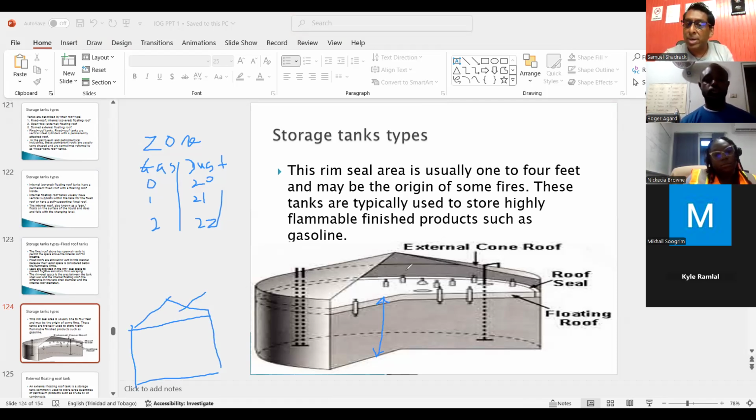So in the aviation fuel industry, they have another roof on the fluid level that cuts off the headspace, so that if there's oxygen here, this roof takes care of that. It doesn't allow the oxygen to get in contact with the fuel level. It's called an internal floating roof tank because this roof is inside of the other roof. However, there's another type of tank, which we're going to have a look at now. If I could get this slide to move, it's called an external floating roof tank.